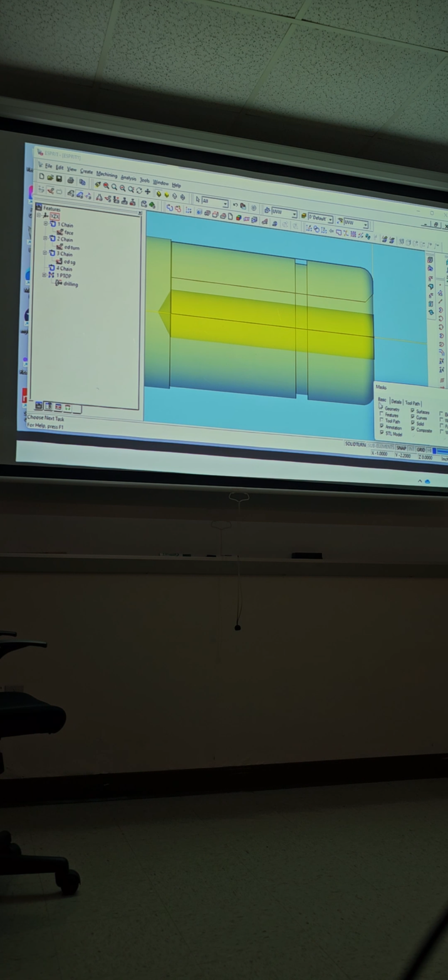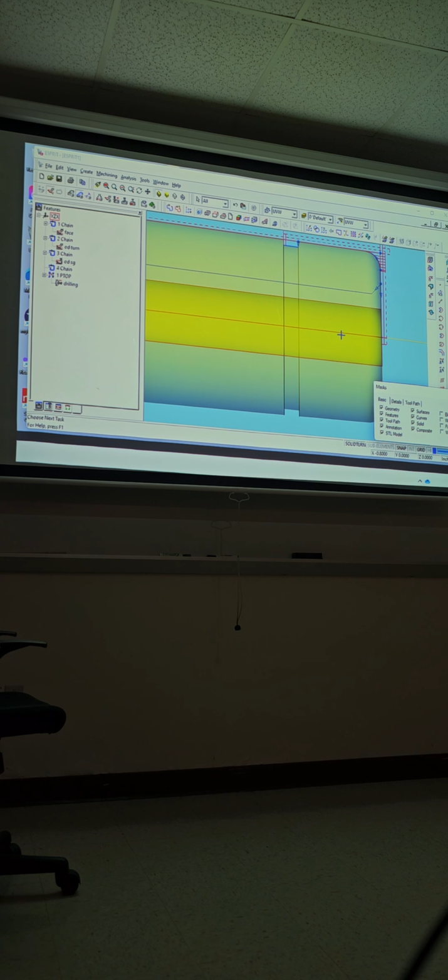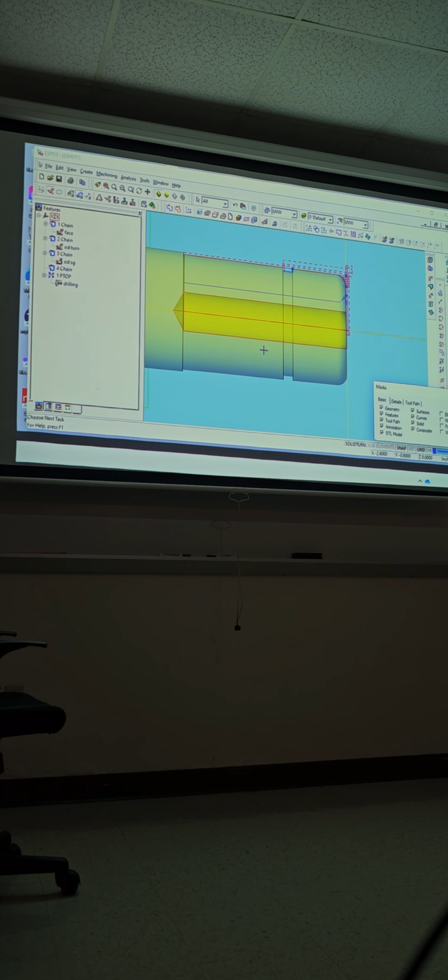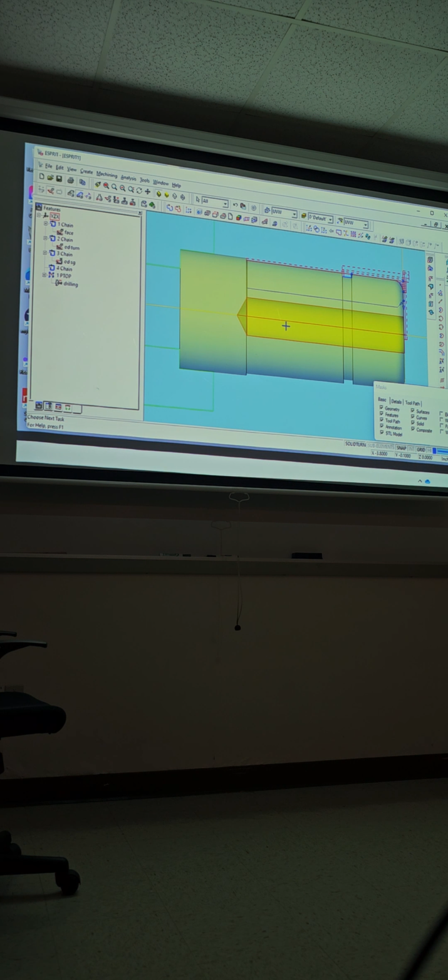So create features, auto chaining, lathe stock, basic features to path off. And remember, it's going the right direction, right? So mine, I'm going from the face back. If you go from here to the front, remember, I don't really like that way. But you can make it. It's a free country. Well, not for veterans. But remember, it's kind of scary whenever you go all the way in a rapid movement, especially in an ID. I won't do that. 100%.